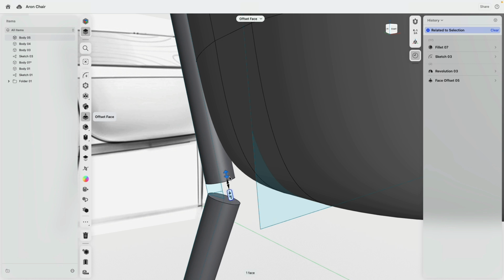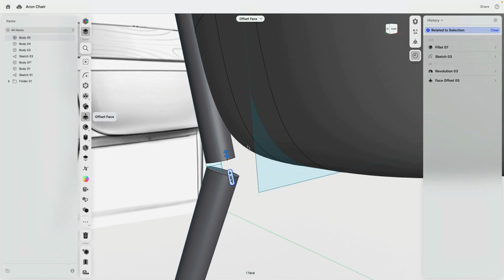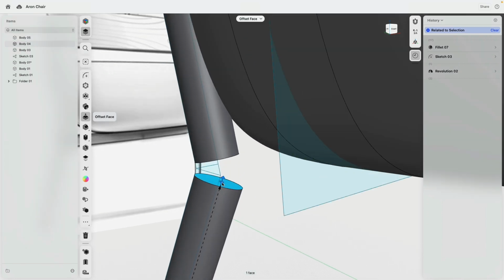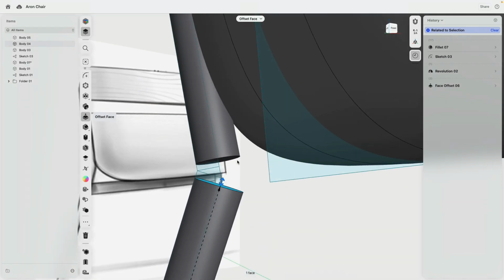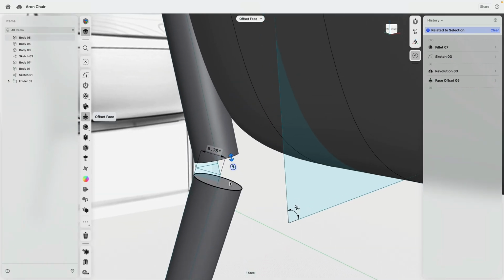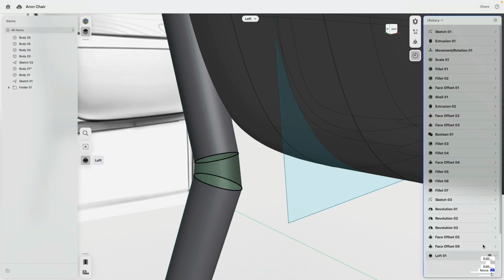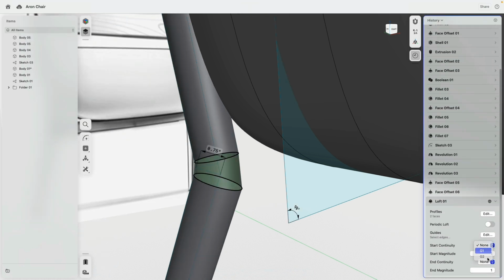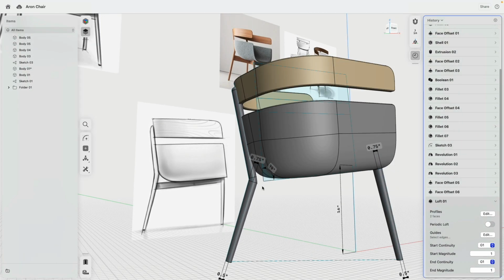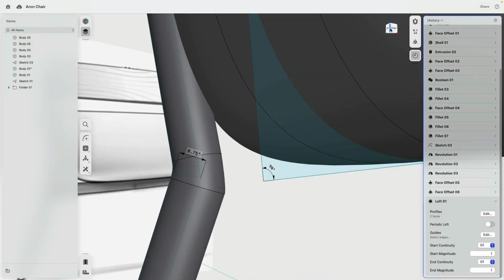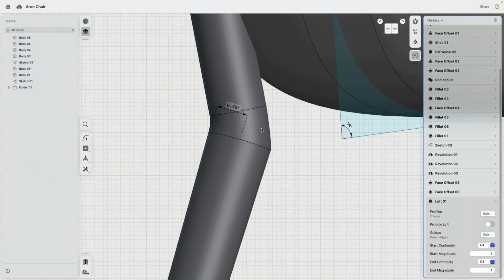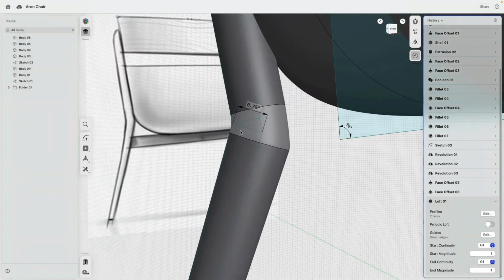How do we do the blend now? That's actually not too complicated. These edges I push back a little bit, and then I say U to U, draw loft. G1, G1, yeah. There it lofted this actually just a little bit.